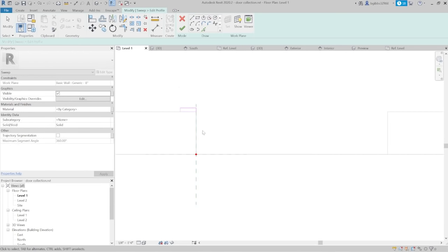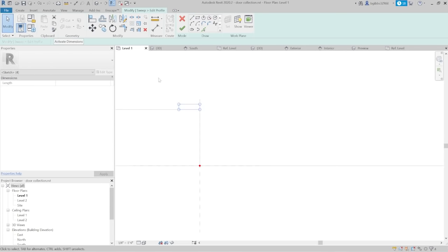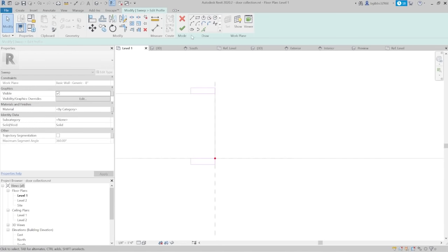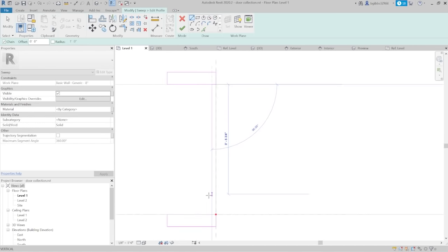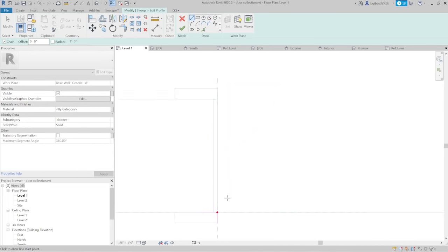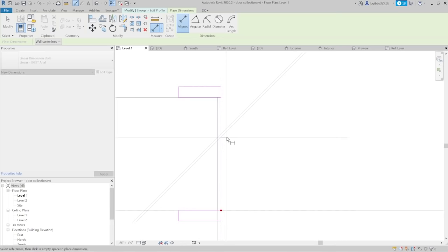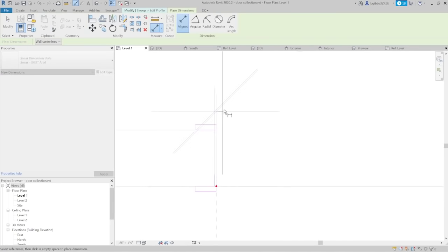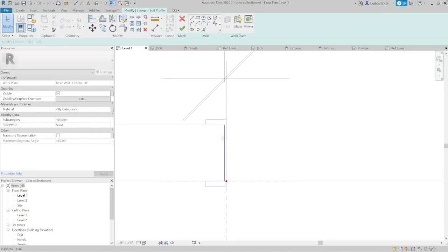A lot of times for the trim, people don't put it in the doorway, which makes a lot of sense. But they actually cut out from the wall for the trim. So I'm actually going to make a small incision. I'm going to pull back the wall that same amount for my opening. This is going to help render appearance. So it's 1/4 inch. That's good.